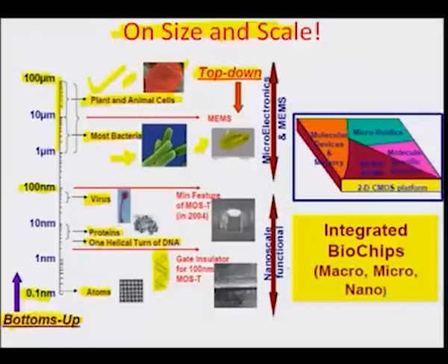So you can recall this as a diving board in a swimming pool kind of structure. The only difference here is that because it is micro scale, this lip is about tens of microns, the thickness could be about 200 to 300 nanometers, and the depth of the cavity can be close to about 1 to 2 microns.